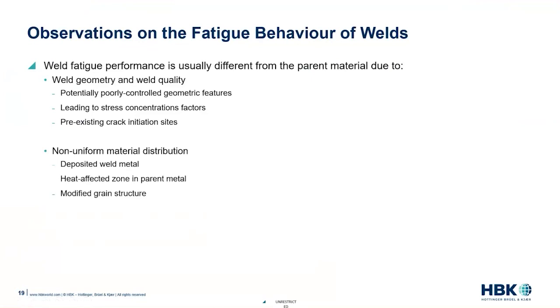Non-uniform material distribution, where we have deposited weld material, we have heat-affected zones from the heating and the cooling of the welding process, leading to modified grain structures. And most significantly, high residual stresses as a result of the welding process.